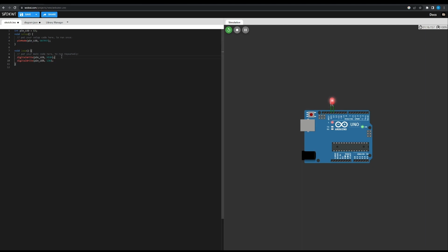We need to add in a time delay between the two digital writes. So we'll add in a time delay here, and then a second one after the second digital write. So we'll say delay parentheses, and in the parentheses we'll add in the input of 1000. Here 1000 is in milliseconds. So what we actually mean by this line is adding a delay of 1000 milliseconds between each digital write. So when we rerun this code, we'll see that the LED toggles and we can see the difference. And there we go. That's our project, and we accomplished what we wanted to achieve in the beginning.